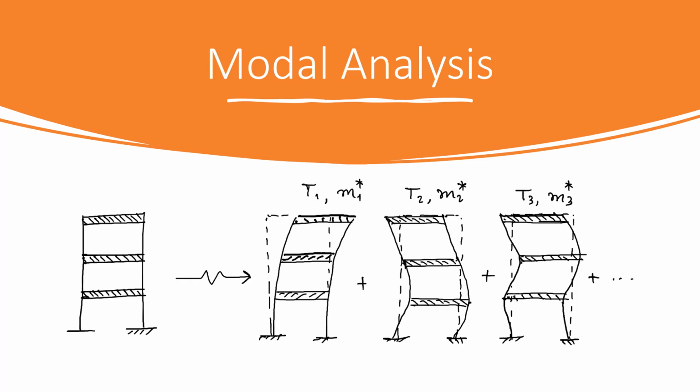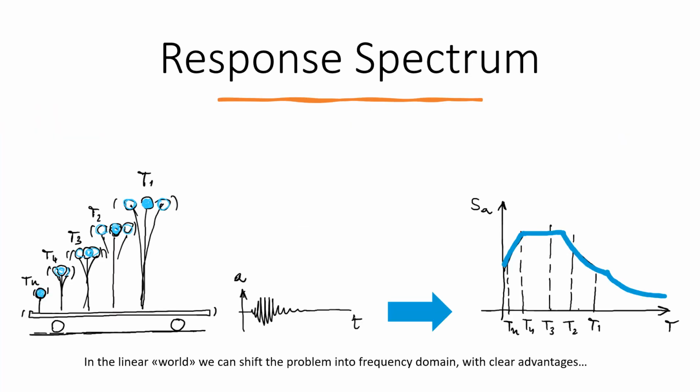Another advantage is that also the representation of seismic input can be simplified and generalized somehow. The introduction of response spectrum is a big advantage and a big simplification that actually builds on this linear world paradigm. And in the linear world, we can shift the problem into the frequency domain with a number of advantages.